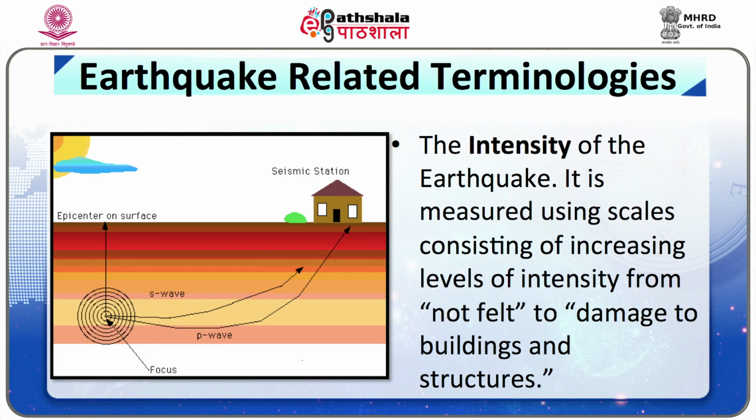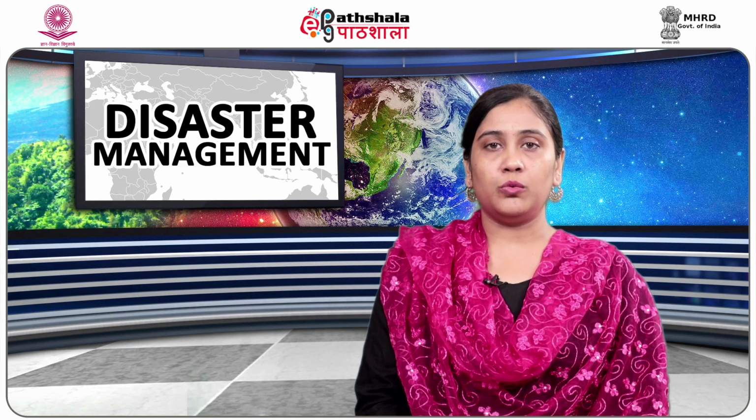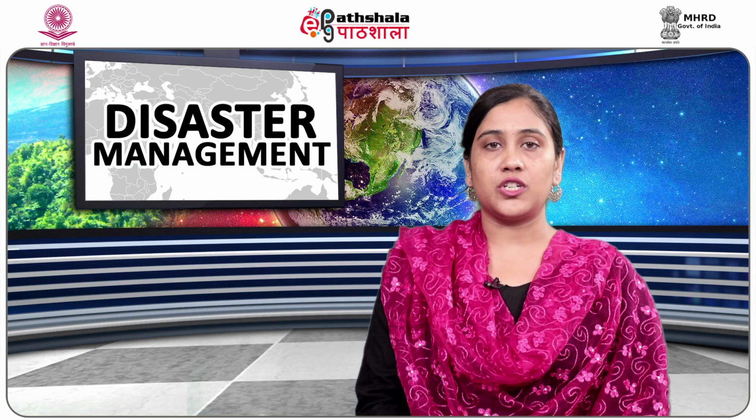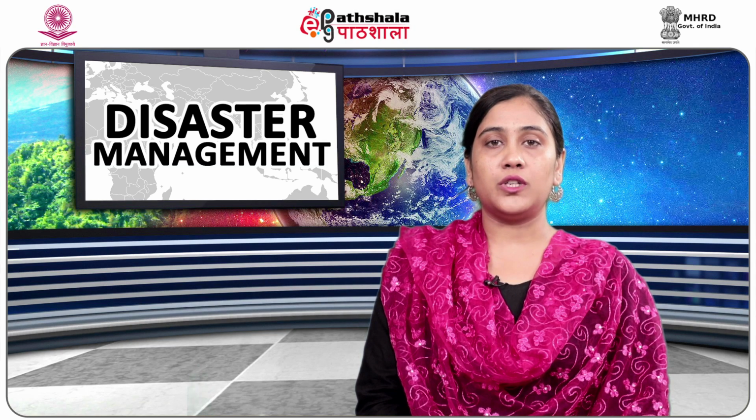The impact or effect of an earthquake of a particular magnitude on the earth's surface is the intensity of the earthquake. It is measured using a scale consisting of increasing levels of intensity from not felt to damaging buildings and structures. Modified Mercalli intensity is the predominantly used scale. The relation between the magnitude and the intensity varies. A 6.0 moment magnitude earthquake in a desert region would have limited intensity due to the absence of settlement, whereas even a 6.5 moment magnitude shallow earthquake near an urban center would have higher intensity.